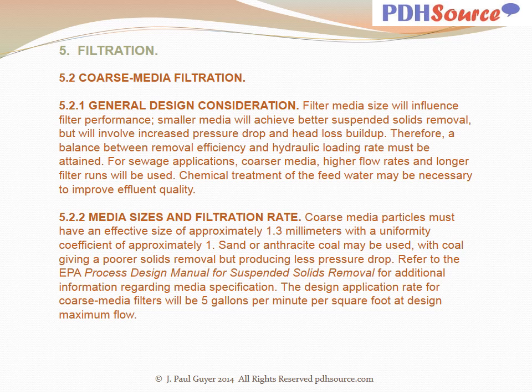With coarse media filtration, certain general design considerations apply. Filter media size will influence filter performance. Smaller media will achieve better suspended solids removal but will involve increased pressure drop and head loss buildup. Therefore, a balance between removal efficiency and hydraulic loading rate must be attained. For sewage applications, coarser media, higher flow rates, and longer filter runs will be used. Chemical treatment of the feed water may be necessary to improve effluent quality.